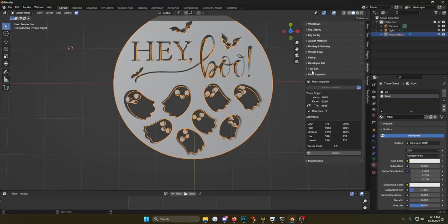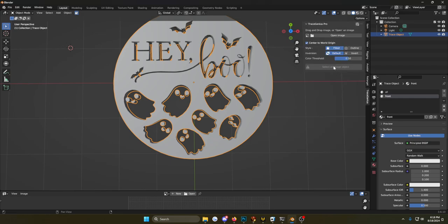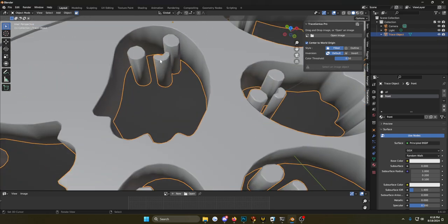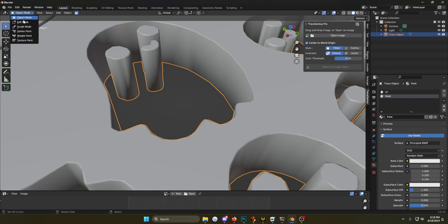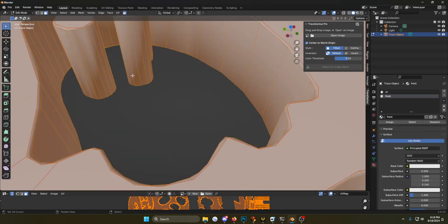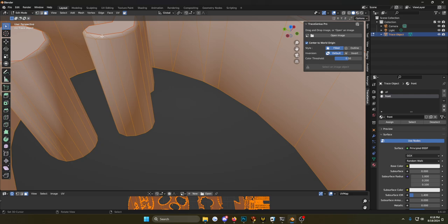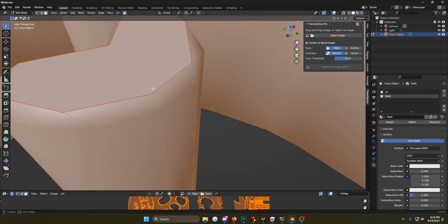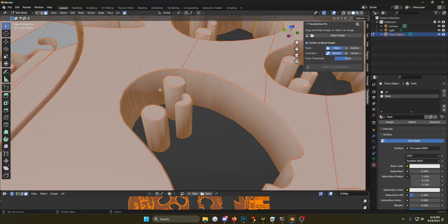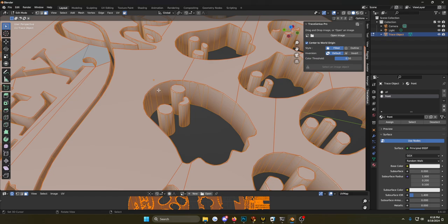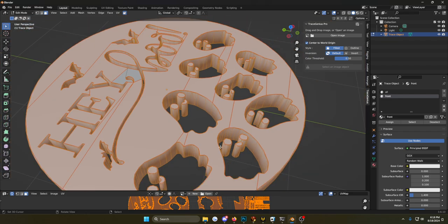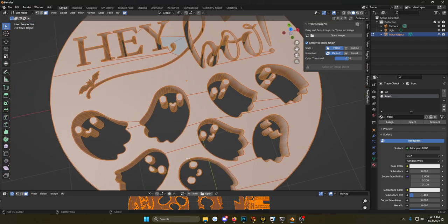What really affects the LI is when we were doing the Trace Shape in the geometry, the resolution of the bevel. Because when you do the bevel, it adds all sorts of vertices in the area where the bevel is. You don't see it now because we've decimated it so much, but that bevel has got lines, lines, vertices, vertices. But that is Trace Shape.